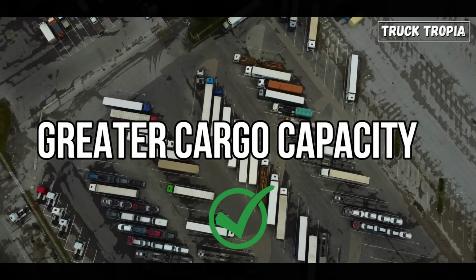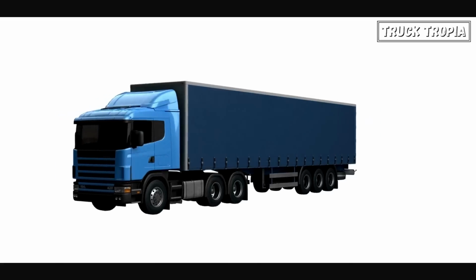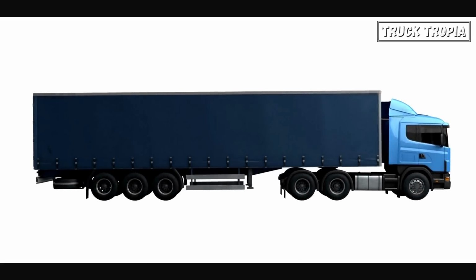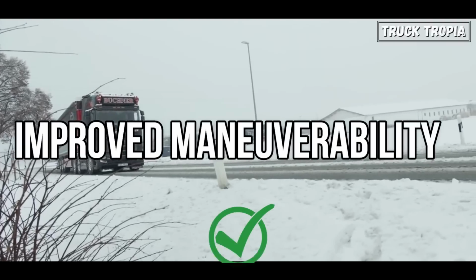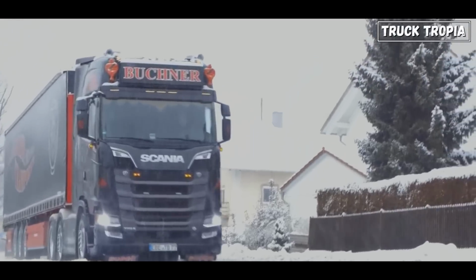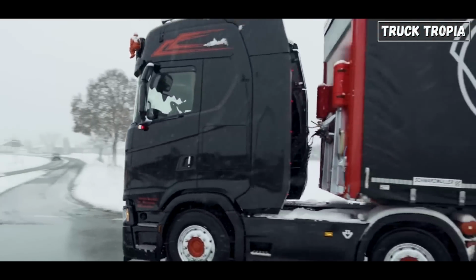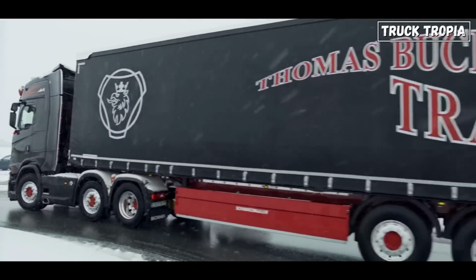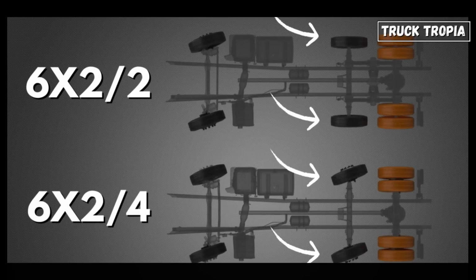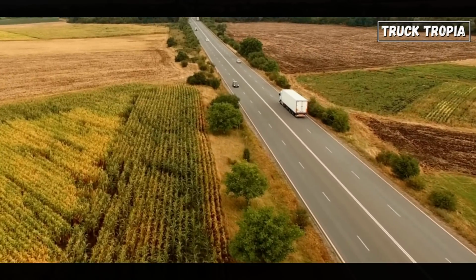Greater cargo capacity. The lighter weight of the 6x2 configuration allows for a greater cargo capacity, which can translate into higher profits. Improved maneuverability. A 6x2 truck has a shorter wheelbase and is generally more maneuverable than a 6x4 truck, making it easier to navigate tight spaces and narrow roads. Also, the third axle can be selected as rotatable, which gives even more improved maneuverability.